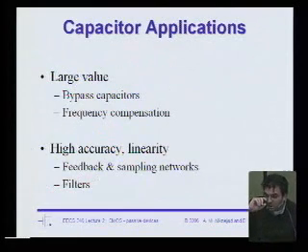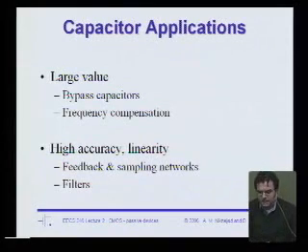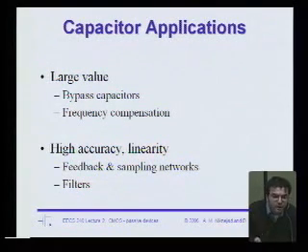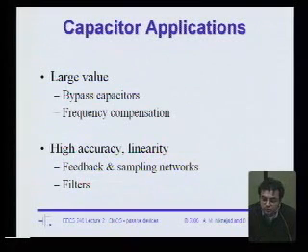All right, so let's talk about capacitors. Now, capacitors are also ubiquitous in integrated circuits. Large value capacitors are needed all over the place as bypass capacitors. You can think of them as your local battery inside the chip that's close to the circuit that's drawing the current, right? The further away you are from your source, the more inductance and resistance there is, and therefore the more supply bounce that you get. So in order to mitigate supply bounce issues, you have to have a capacitor nearby as a reservoir of energy.